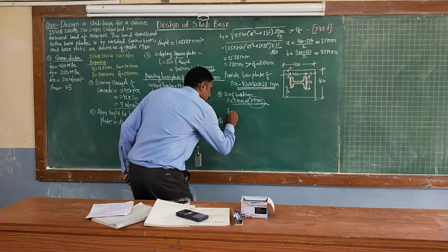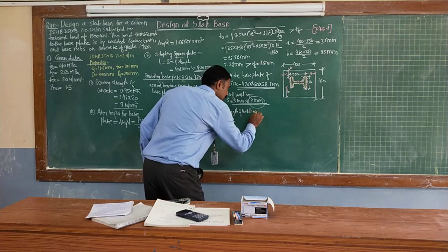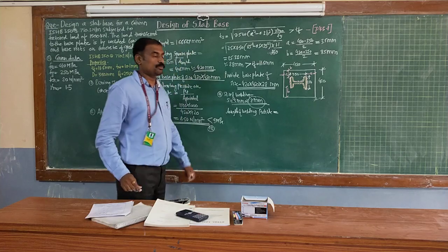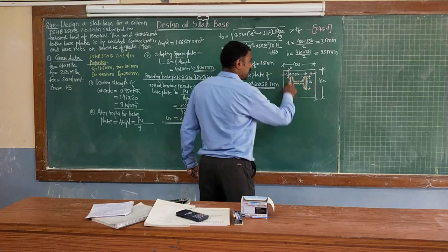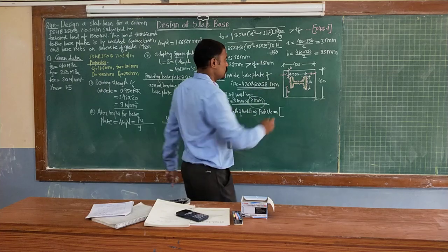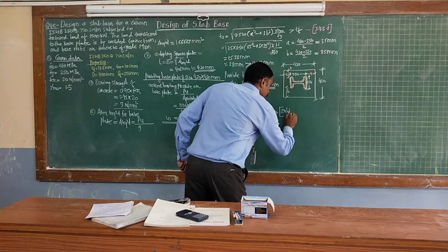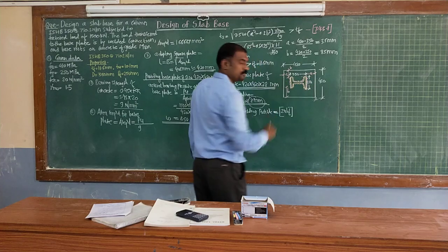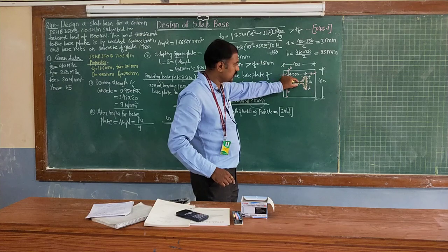Now the length of welding possible. At what particular length can we provide the welding here, so that you have to calculate the length. Initially the formula is simple, just calculate the perimeter. So this is width of flange, again width of flange, 2 times width of flange. So 2 times BF is the first calculation. Again from the inner side also you may provide the welding. What this inner side is: it is width of flange minus thickness of web.